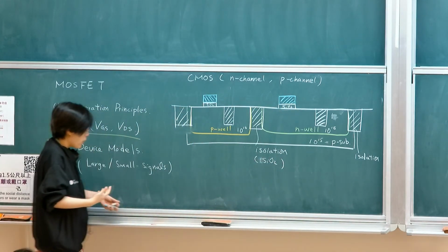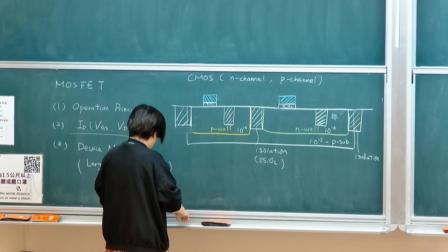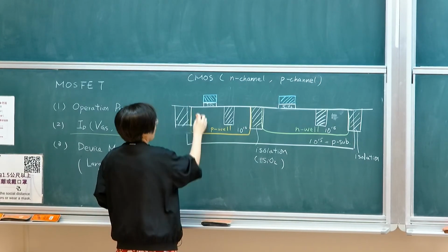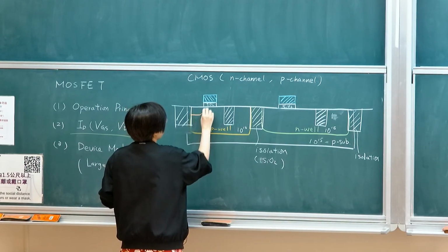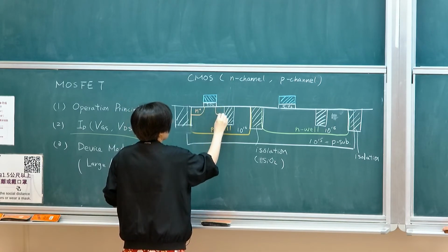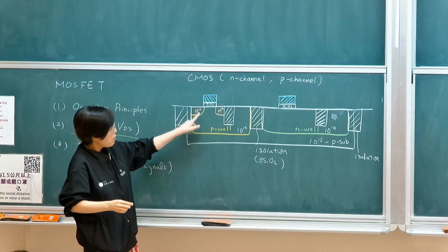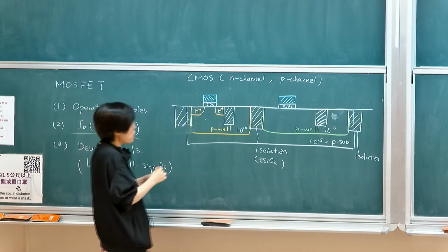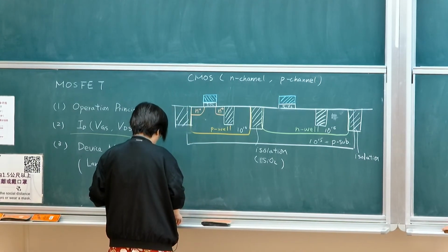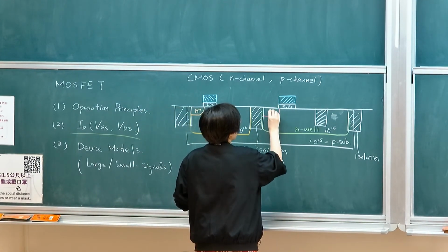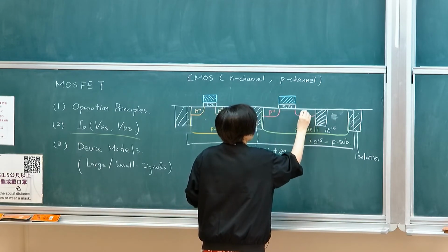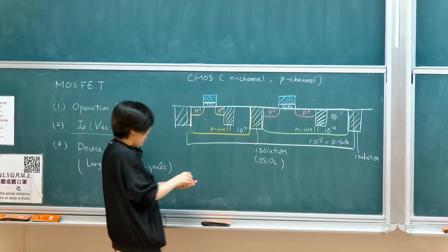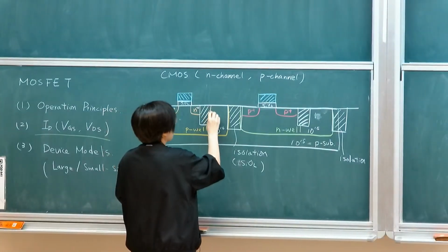And then I'm going to make my source and drain. So for N-type, this is the N plus. Remember, you're creating NPN so that it will not conduct at the beginning without the channel. So you want to make sure that happens. For P-types, we have P plus. And then for pickups, you want to do the same type. So this will be P plus pickup.